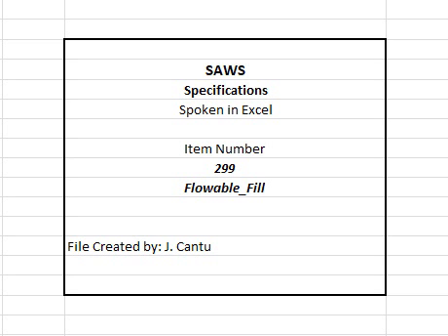Fill an open-ended, 3-inch diameter by 6-inch high cylinder to the top to test the consistency. B. Immediately pull the cylinder straight up. The correct consistency of the mix must produce a minimum 8-inch diameter circular spread with no segregation.